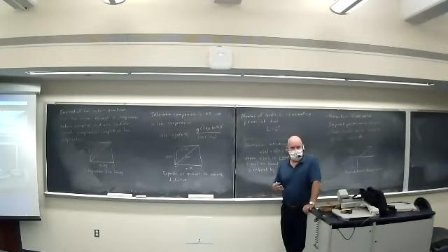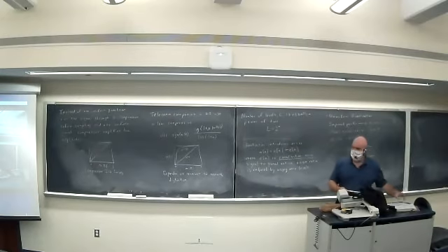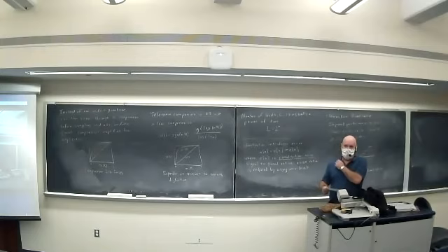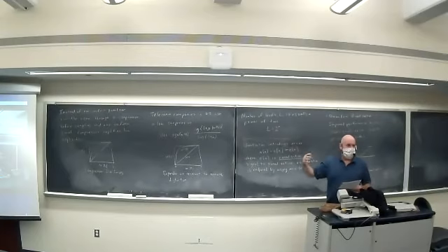They use it in Japan also. I think in Europe they use a slightly different curve called A-law compression and expansion. But it's a common technique. Again, it's this same concept of introducing deliberate distortion at some point so that we get better performance in the presence of noise, or in this case, improving the subjective performance of our quantizer.